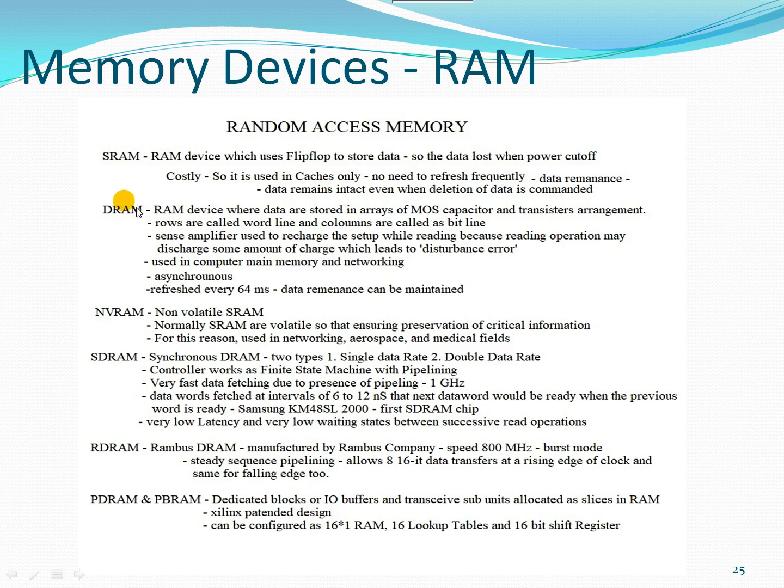Because DRAM is the counterpart of this SRAM. In DRAMs we use MOS capacitors and transistors for data storage. For those RAM devices we need frequent refreshing of the data, because the MOS capacitors are leaky in nature. The frequent refresh is needed because long-term storage is somewhat difficult in the case of MOS capacitors.